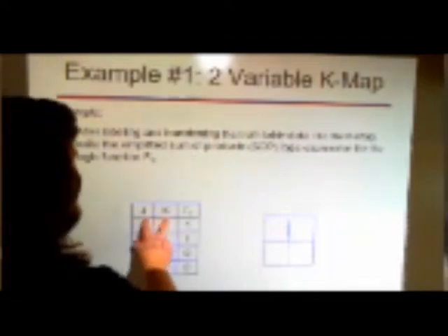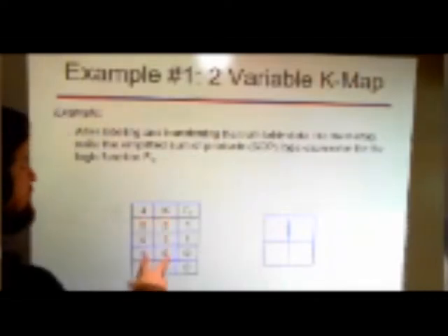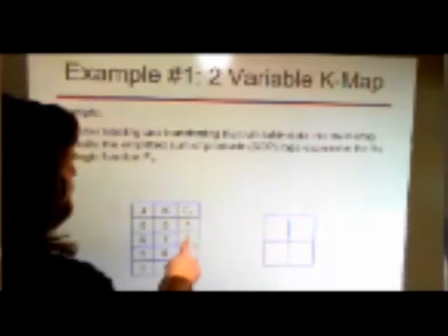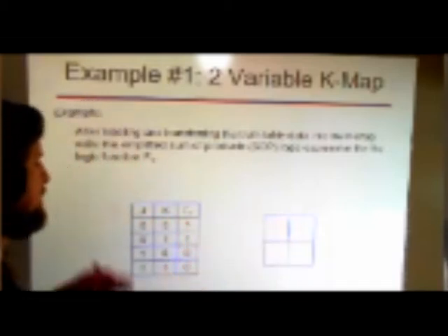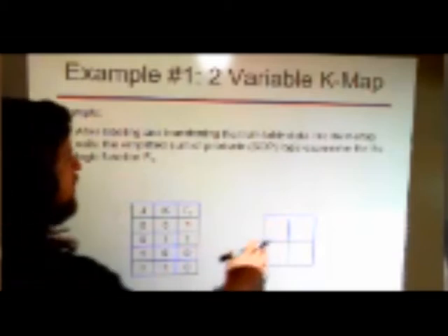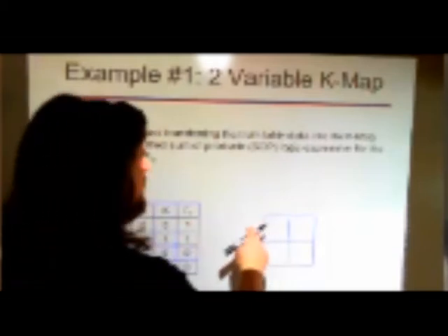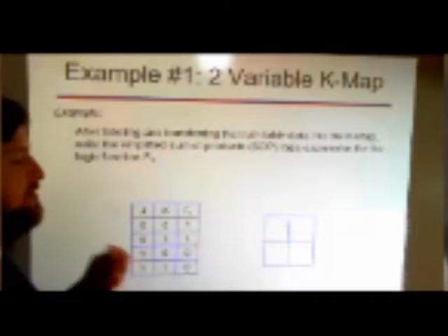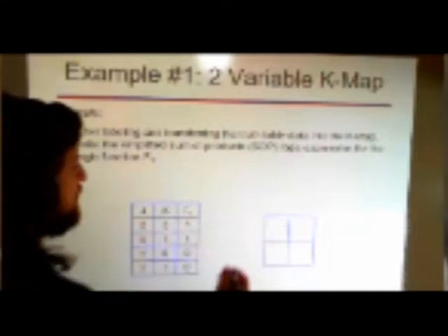For a 2-input K-map, right? Or for a 2-input truth table, our K-map will be a grid of 4. It's because we have 4 possible combinations. In our upper left-hand corner, this is important, we will always start with the nots, the zeros. We're always starting with this term.